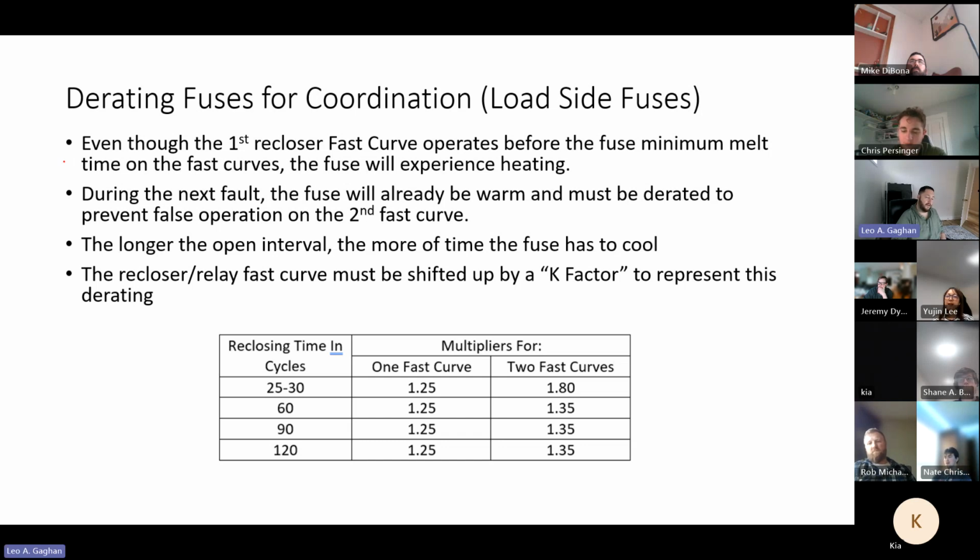With that, a lot of times we'll do something called reclosing, where let's say you had a temporary fault, and maybe a squirrel touches the line, right? You trip, squirrel burns, falls to the ground, breaker recloses, squirrel's gone, you're happy. So that's why we have reclosing.